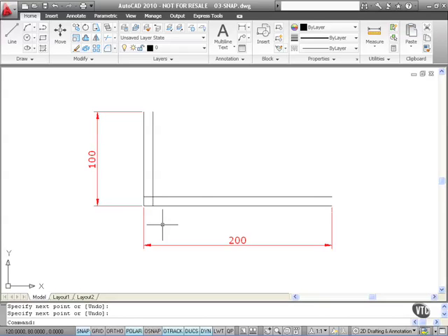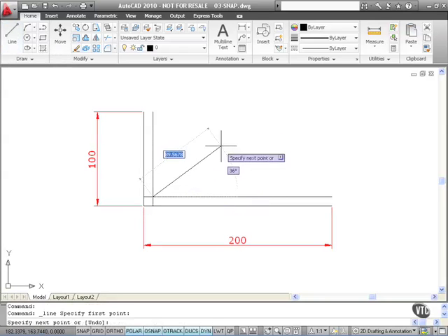If I switch it off though, watch. Just click on it to switch it off, look. I now can't snap to anything, so what I do now is I go back to OSnap, switch that on, and I can now draw a line, let's say from the intersection of those two lines there. So you can see that Snap has its purpose for regular increments, regular objects that need to be drawn. Object snap allows you to work from a relative viewpoint where you're snapping relative to existing objects in AutoCAD.